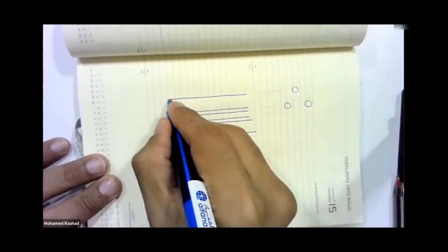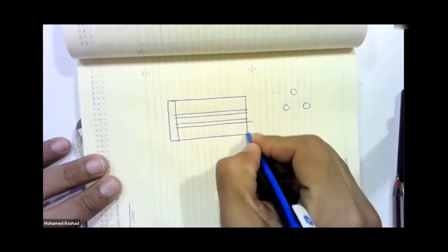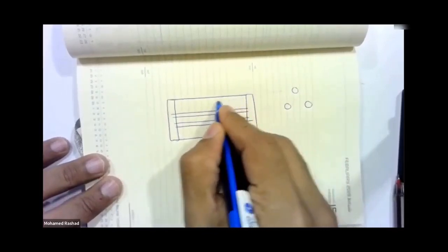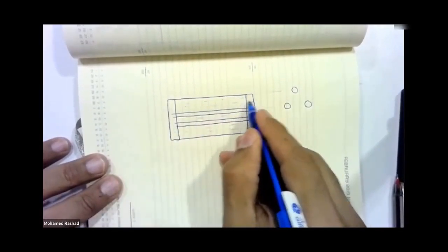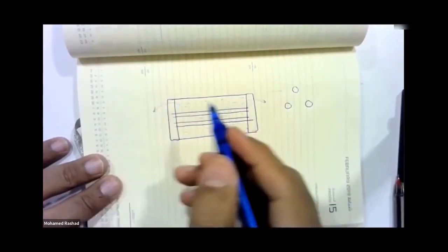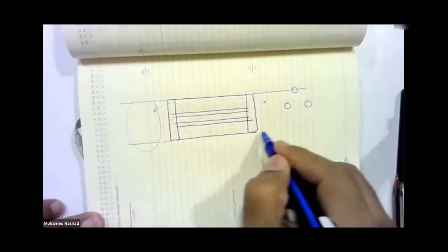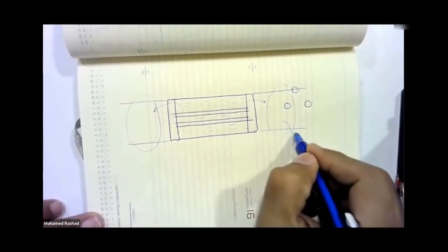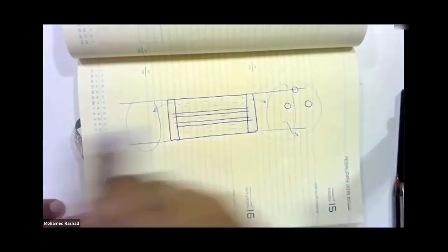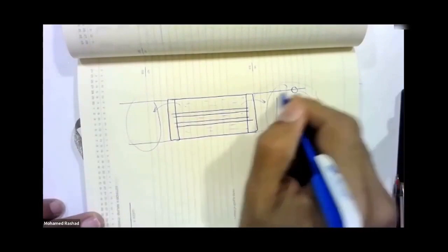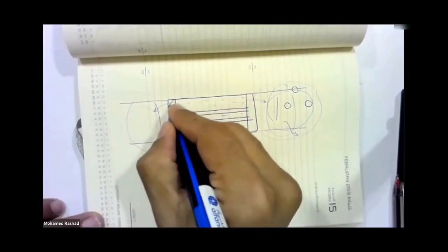Nice, okay? Here, this is the place we call a gas tight spacer. What does gas tight spacer mean? It means this place is sealed, and therefore the SF6 gas, the compressed gas we're talking about, will be here. This is not connected to the gas in this area or the gas in that area. Therefore, if there is a crack in this compartment or that compartment, the leakage in the SF6 gas is not related to the entire gas system, but only to this compartment alone. The increase or decrease in pressure is related to this compartment, not to this one, nor to the one next to it, and so on.